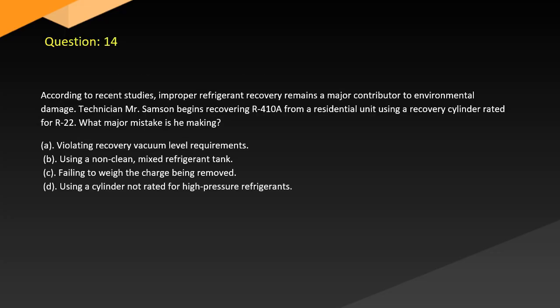Question 14. According to recent studies, improper refrigerant recovery remains a major contributor to environmental damage. Technician Mr. Sampson begins recovering R-410A from a residential unit using a recovery cylinder rated for R-22. What major mistake is he making?